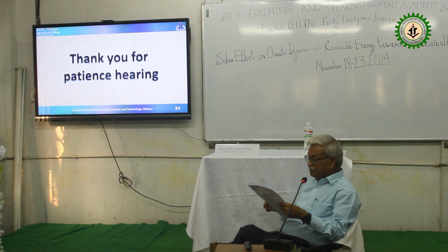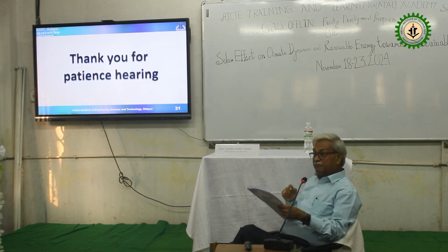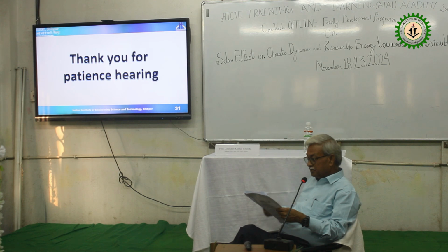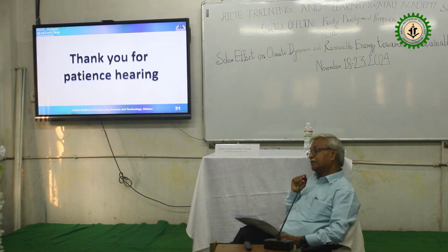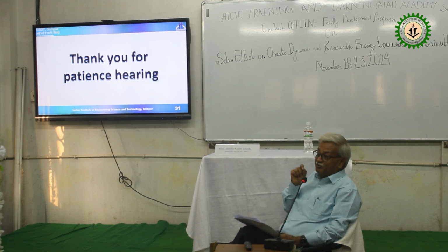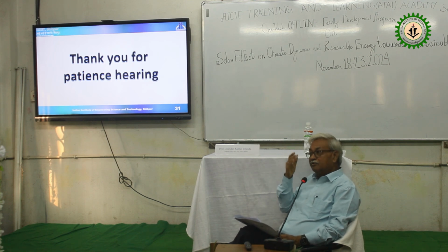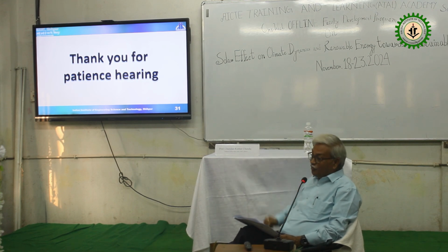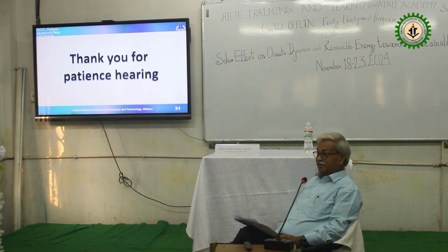So the number of frequency monitoring nodes available to measure frequency deviation across different areas of the power system matters, especially in our country, the 7th largest country on the planet, with a huge geographical area. Post-disturbance frequency deviation is not uniform. Before the disturbance, if you measure the frequency at different nodes, you get more or less the same good value. But just after the disturbance, at a few nodes you will get a good idea because those nodes face less disturbance, while in other nodes they are suffering a lot and their frequency deviation is more. This is another factor in estimating the inertia.